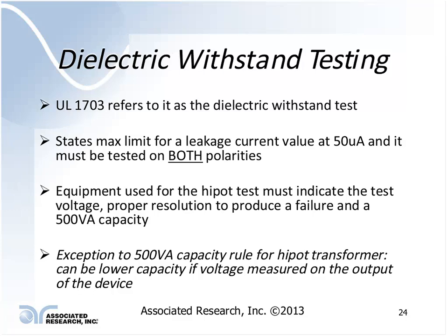So if your voltage drops with a heavy capacitive load, you're technically not testing at full voltage, and you didn't run the test properly. However, if it's regulated on the output and has a feedback loop, ensuring that the output is constant, you don't have to worry about that, which means you don't have to have a very high capacity unit to handle such heavy loads.